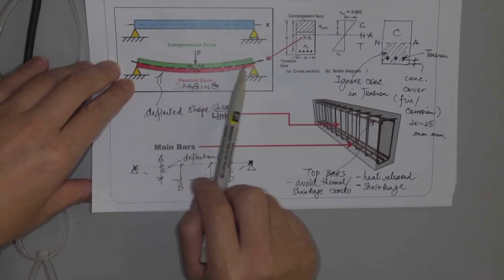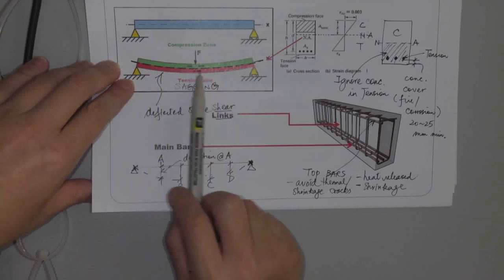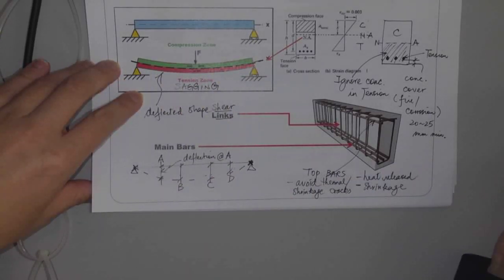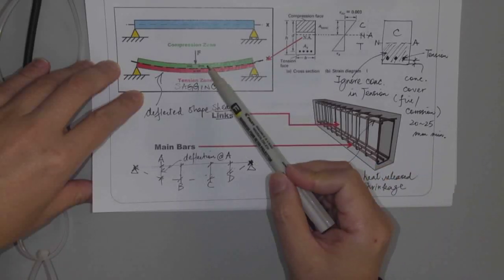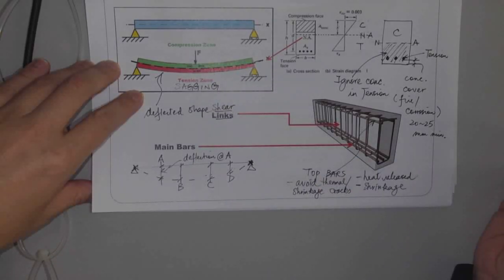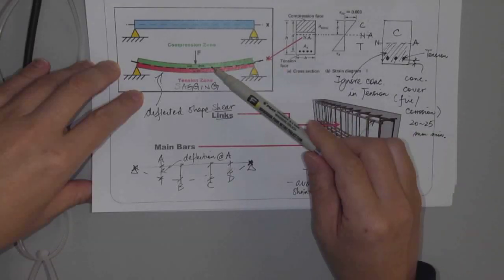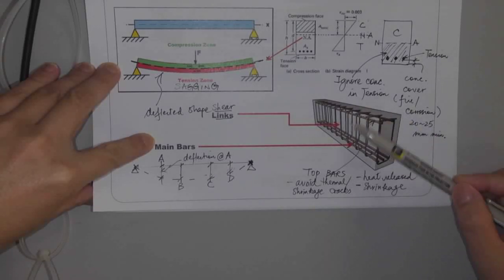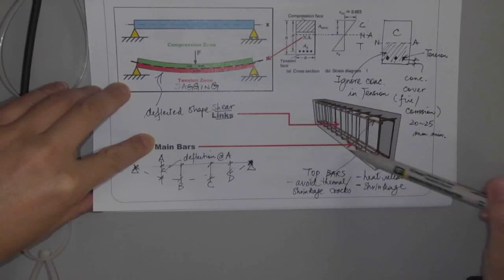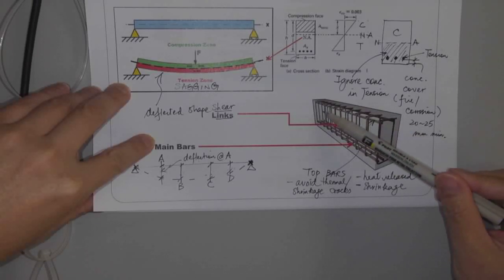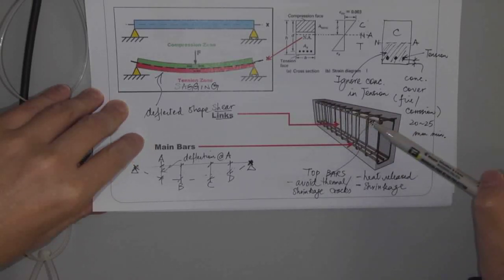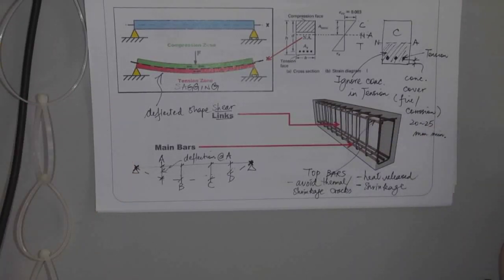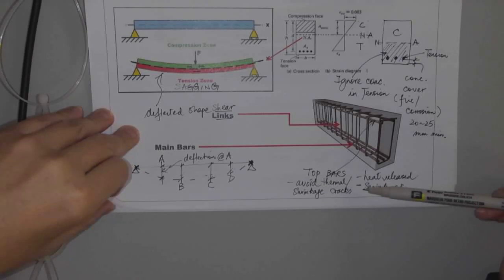Right, you try to sketch the deflected or deformed shape, and from the shape you can tell whether it's sagging or hogging. And from sagging or hogging, you can tell which part is in compression and tension. And then you know which reinforcement is the main reinforcement, the top or the bottom. So in this case, the bottom is the main bars for bending, and the top is secondary, and it's not for bending purposes. That's what we explained last week.